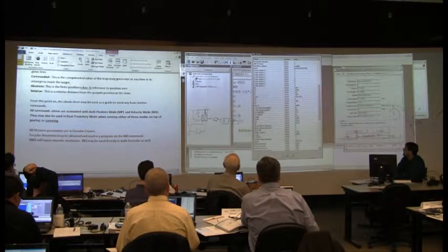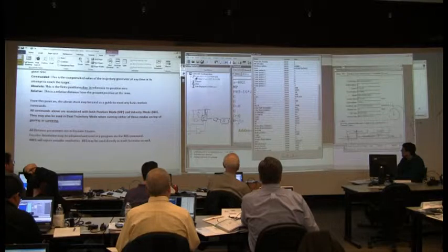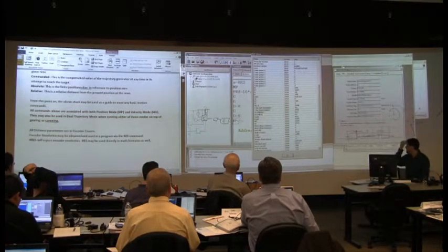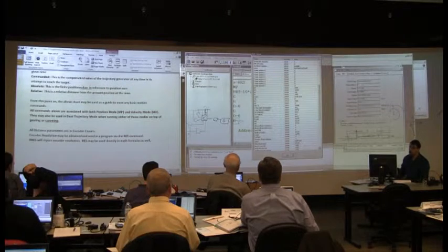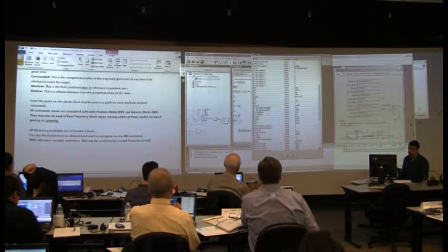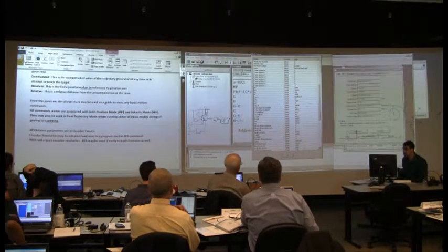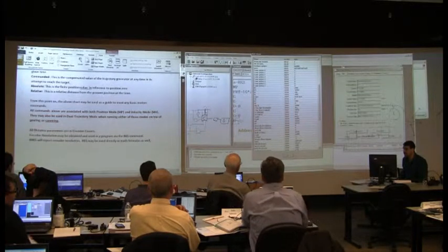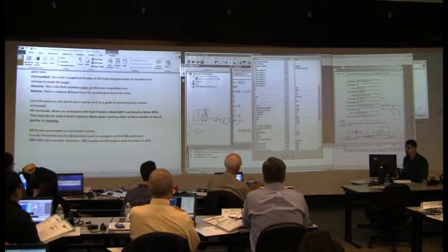Down here you see V-bus high threshold divided by 4. What's 4 times 18? That's 72 volts. This motor is shipped with that, 4 times 18, yeah, that's 72 volts. So the motor will trip offline at that voltage. It will literally say, I got a bus over voltage fault if you exceed that. You'll never see it otherwise.